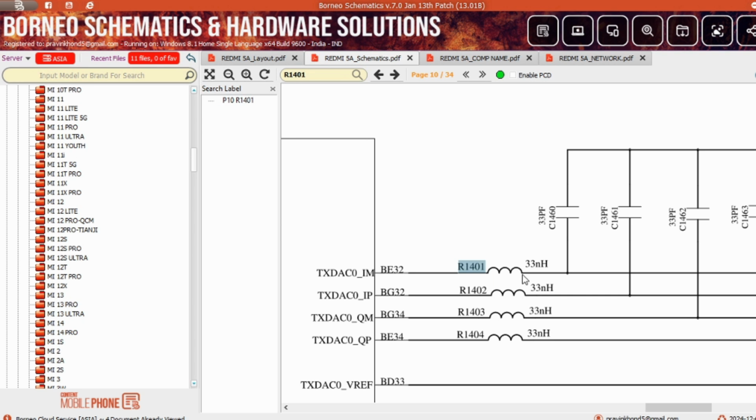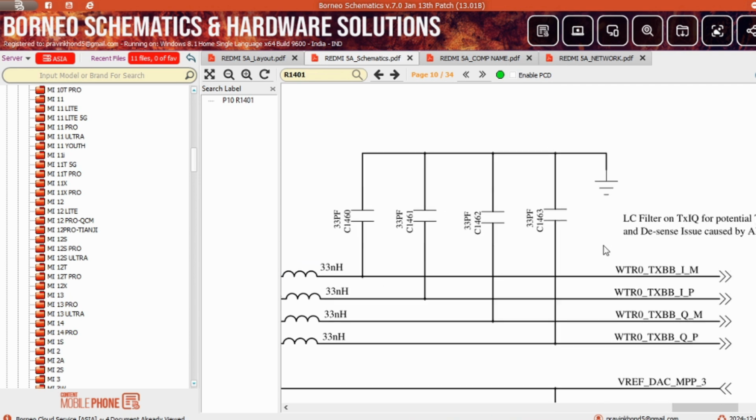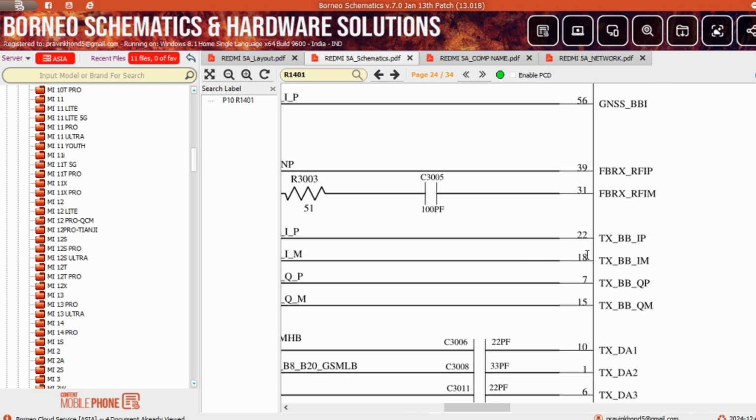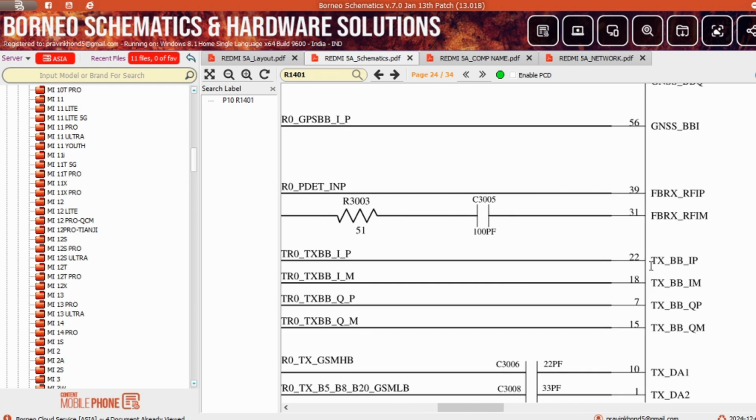If you see this side connected with a diode value, this coil is properly connected. Also, when you open the RFIC, check these points too: pins 22, 18, 17, 15. How? Put one probe on the coil input side where the CPU connects, and the other on the 22 pin, in continuity or beep mode. If you get a beep or 00, that means this line is connected.